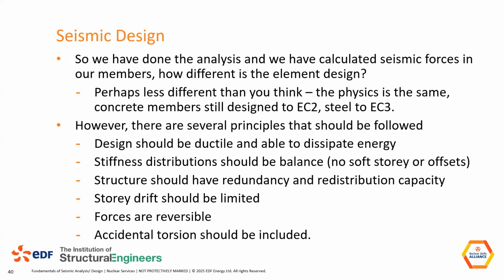For example, if we have steel connections, we can make the connections stronger than the beams so that the moment hinge forms in the beam, and the beam is a plastic section, we can dissipate quite a bit of energy there. So even if we do get local yield, we don't get collapse. So there's a big focus on that, but there are other aspects as well.